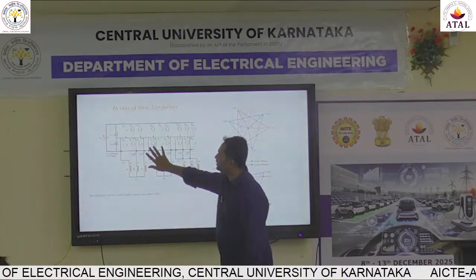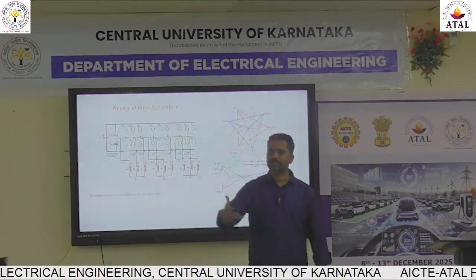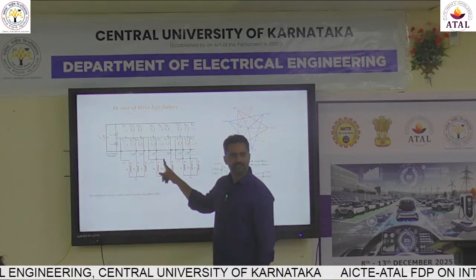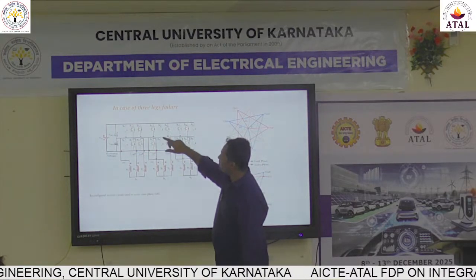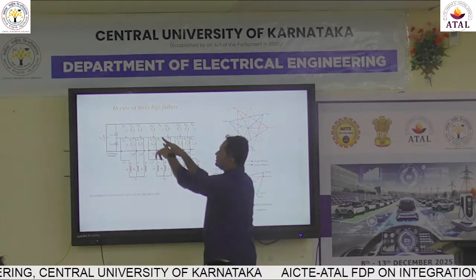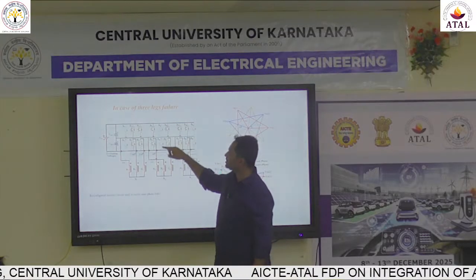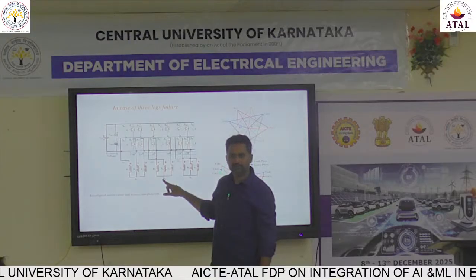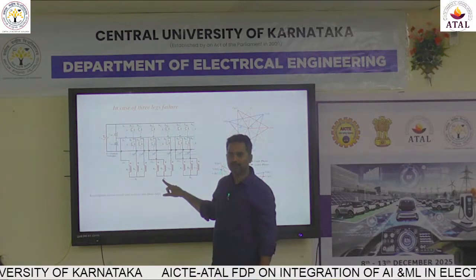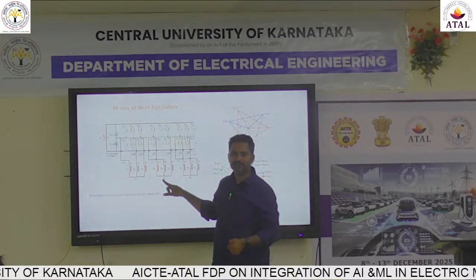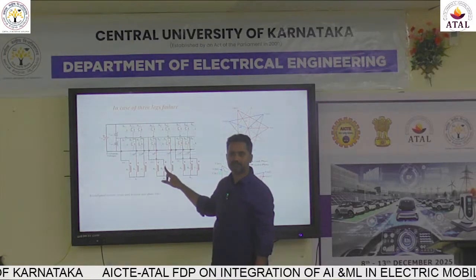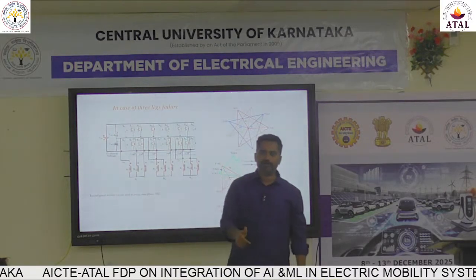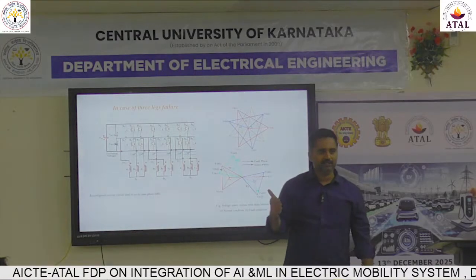And of course not only this, it is very simple. I will give you another example. Why should I connect here? Because I want a 0 for this voltage, is it right? Instead of connecting there, I will connect to this, because this is the one in fault and this is not in fault condition. I will make a 50% duty ratio, then it will not give a 0 voltage, but it will work. But what is the difficulty there? The ripple component is different for this winding compared to this winding. That ripple component, you go back into the small signal.